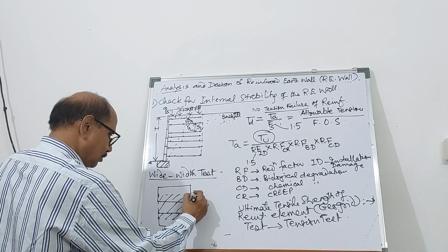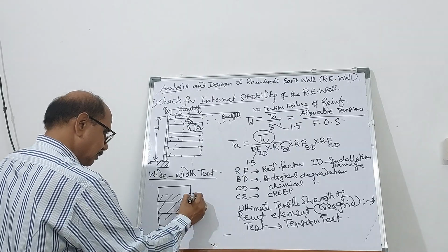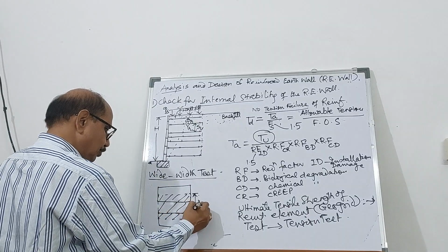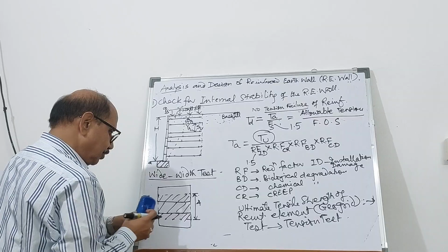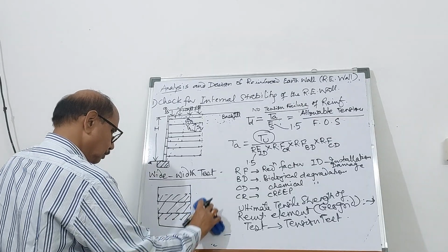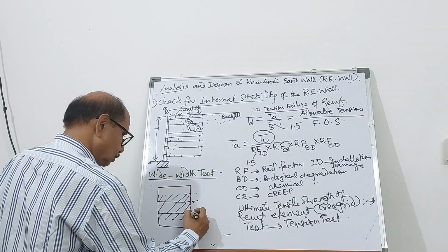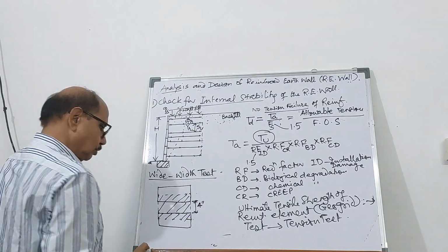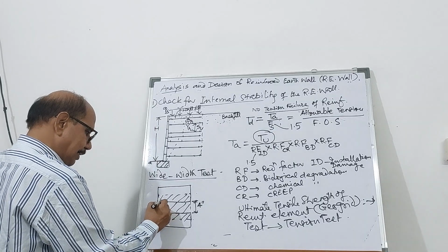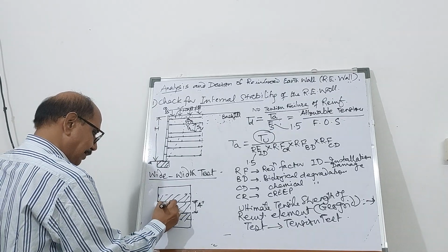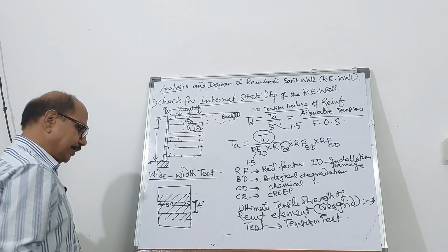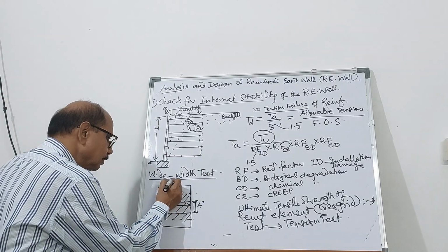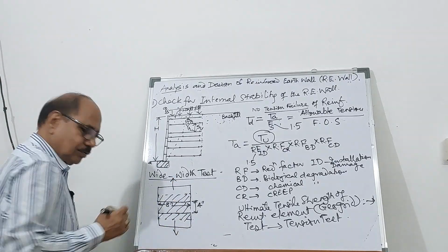So your sample size in wide width test is going to be 4 inch, that is 10 centimeter, and this is going to be 8 inches, that is 20 centimeter. And then you pull it, apply the tensile force,